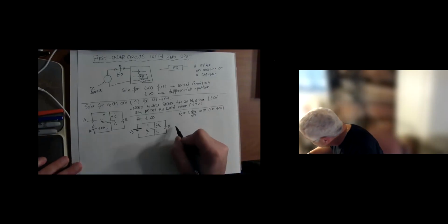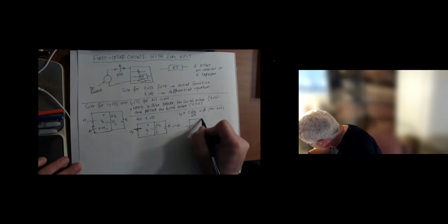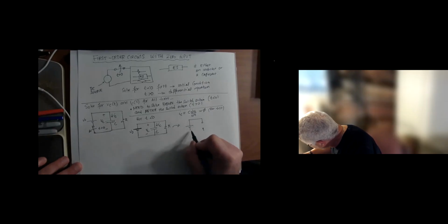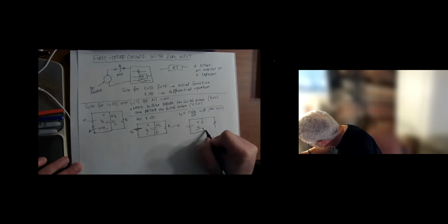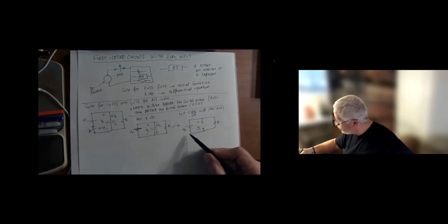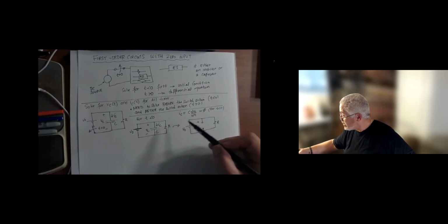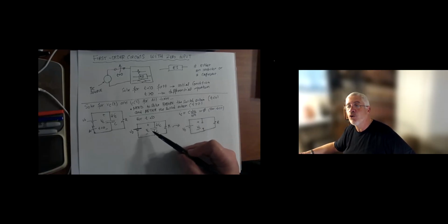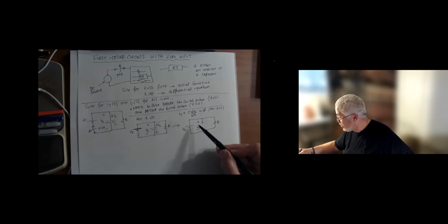So the circuit we're actually solving is this: the battery, the capacitor looking like an open circuit with a voltage VC across it, and the resistor R right there. The capacitor looks like an open circuit because if there has never been a change in any sources for a very, very long time, then everything is constant, so the capacitor current is 0.